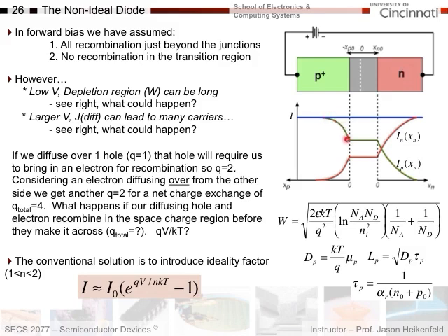And remember, the reason why the hole current dropped off like this is basically the holes disappearing as they recombine with the excess electrons that were brought over. And again, this is P plus N, so I have more holes than I do electrons.